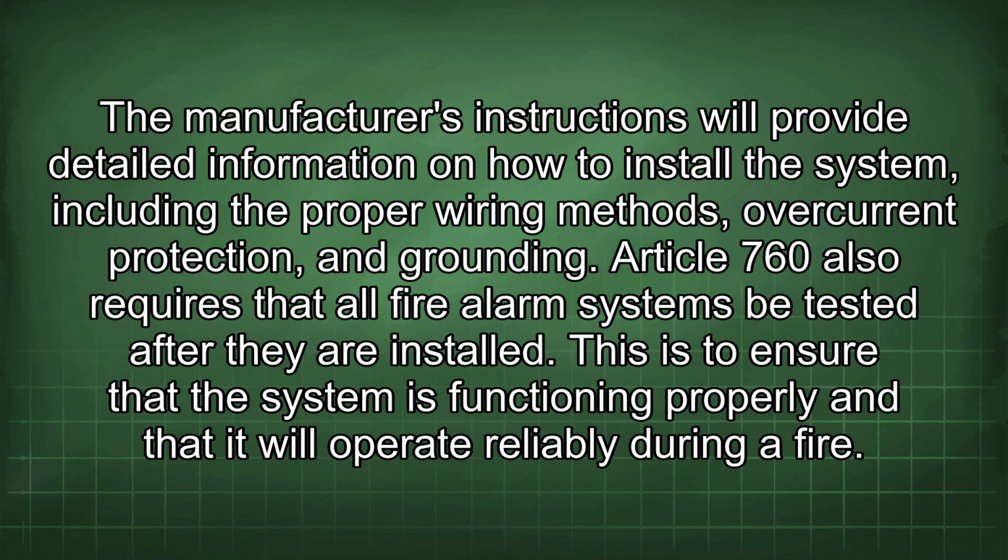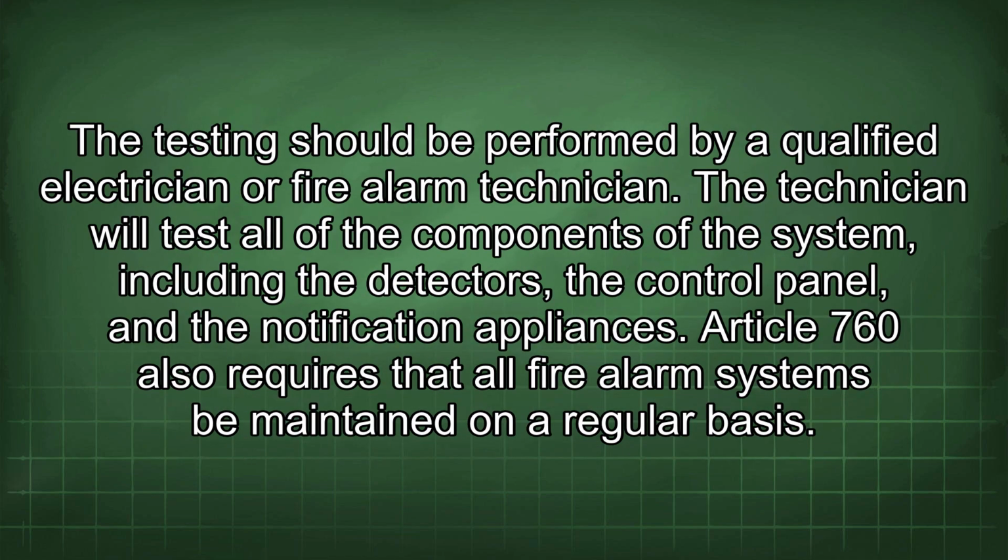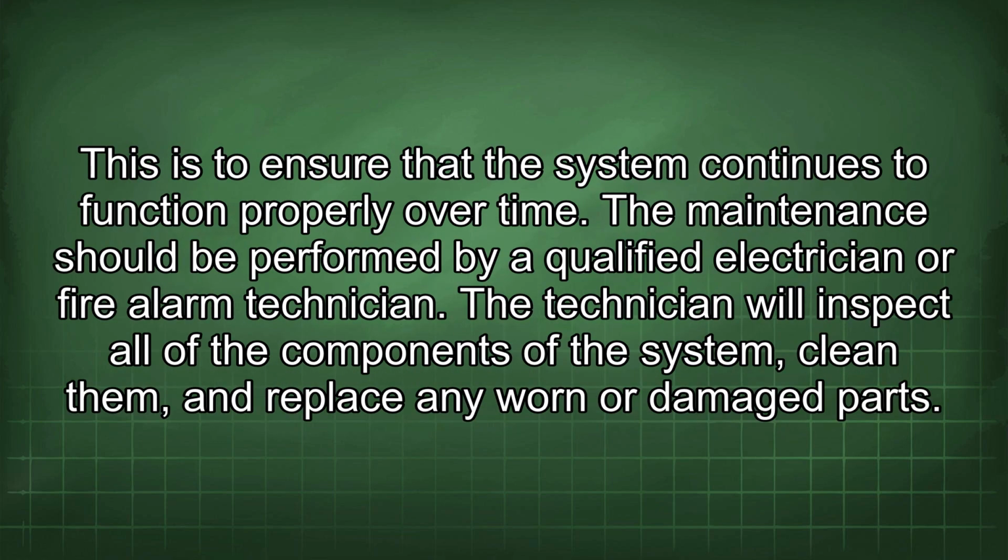Article 760 also requires that all fire alarm systems be tested after they are installed. This is to ensure that the system is functioning properly and that it will operate reliably during a fire. The testing should be performed by a qualified electrician or fire alarm technician. The technician will test all of the components of the system, including the detectors, the control panel, and the notification appliances. Article 760 also requires that all fire alarm systems be maintained on a regular basis. This is to ensure that the system continues to function properly over time. The maintenance should be performed by a qualified electrician or fire alarm technician. The technician will inspect all of the components of the system, clean them, and replace any worn or damaged parts.